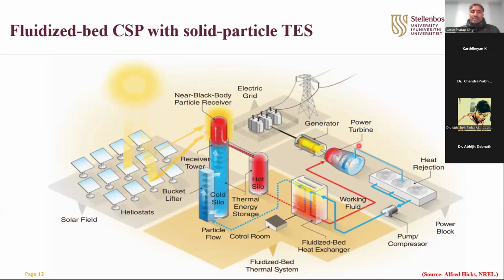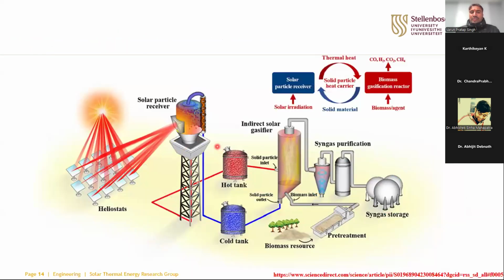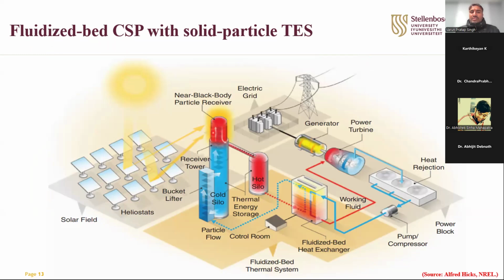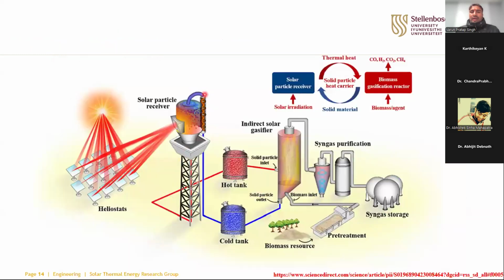So these are the kind of fluidized bed combustion. Those who know about power plants may recognize this particular word. Previously we were using pulverized coal type systems. Now fluidized beds have come into the picture with a very high burning efficiency, and the same concept we are using here. I will tell you in detail what's happening. We are using solid particles for making a fluidized bed, and this concept is there for those working in biomass and biogas. We are basically focusing on either municipal waste or biomass, and again we are burning this over a solid particle receiver.